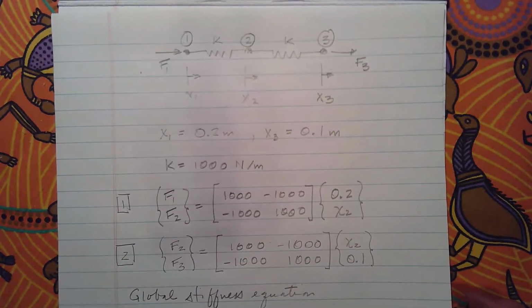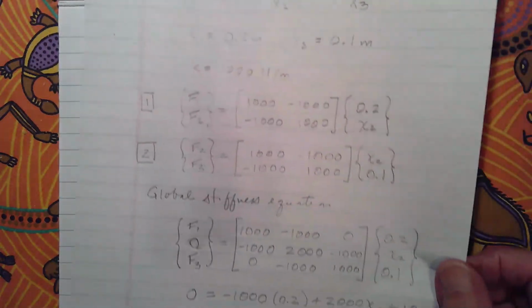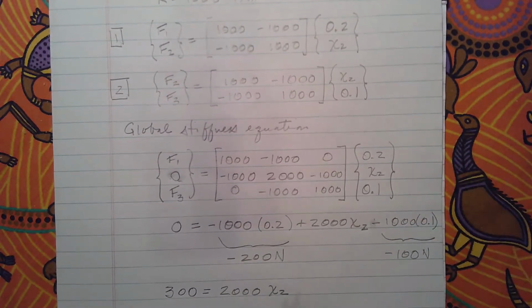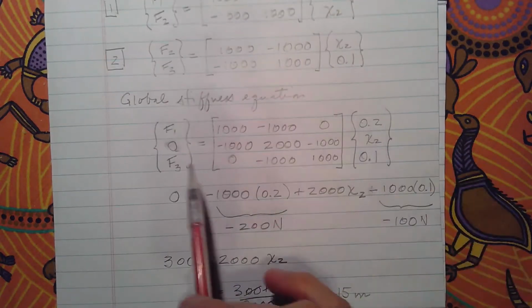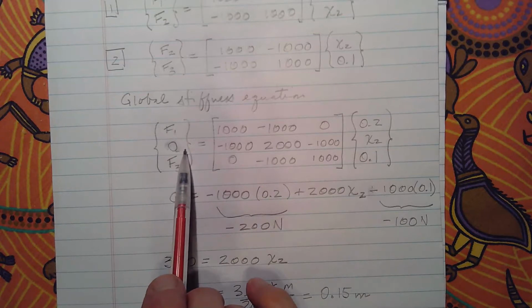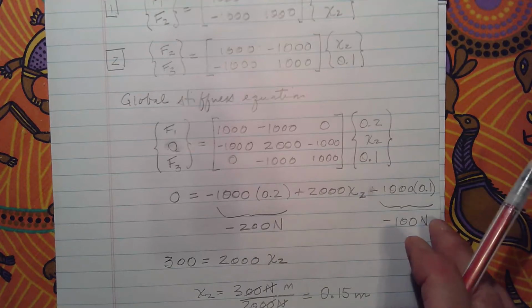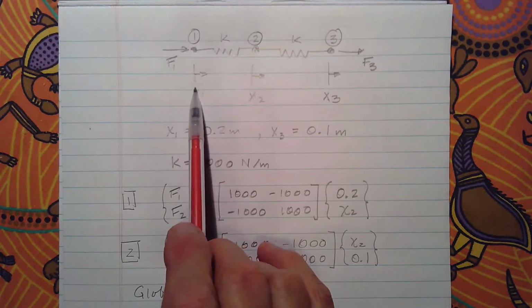Okay, I'm going to continue with where we were before, working this problem here with two end-to-end spring elements. They have the same K, 1,000 newtons per meter, and we got to the point where we had formulated our global stiffness matrix from our element matrices, and we had an unknown displacement, and we used the second equation that's contained in this matrix formulation to solve for x2, and it turned out to be half, or the average of the two end displacements.